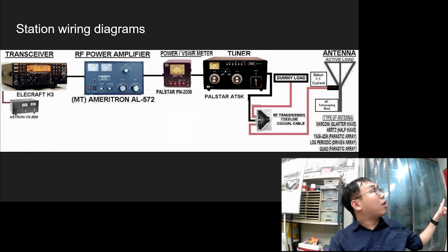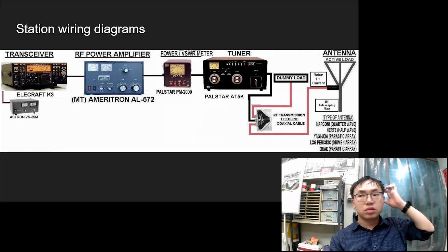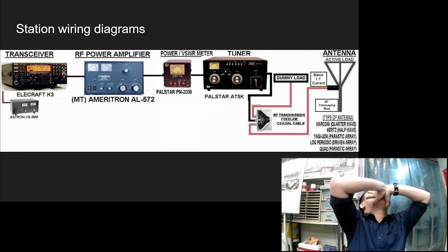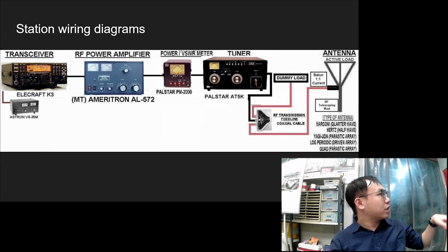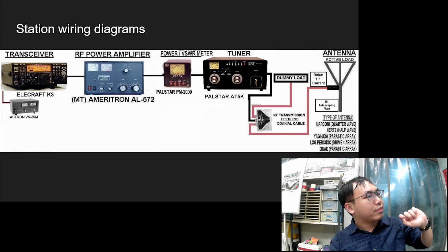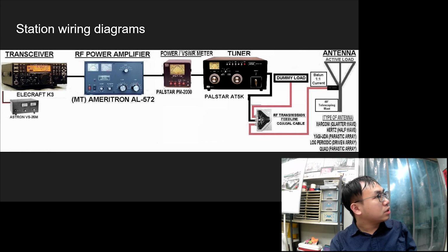Our inverter is connected with a power meter directly, so you can just monitor the power output instead of checking the power directly. And the antenna tuner unit helps you to minimize your SWR by adding inductance or capacitance. Sometimes if you want to check your setup, you connect it to a dummy load. Okay.